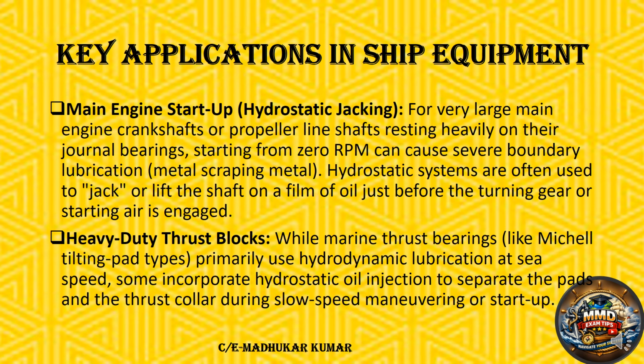Okay. Now we will see another example, which is your main engine startup. When the main engine is going to start, what are the things that happen? Hydrostatic jacking. For every large main engine, the crankshaft or the propeller shaft rests heavily on its journal bearings.